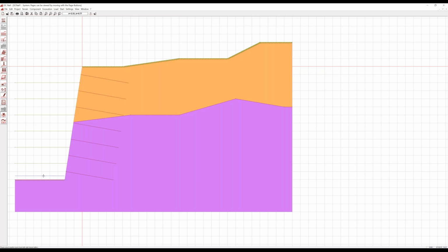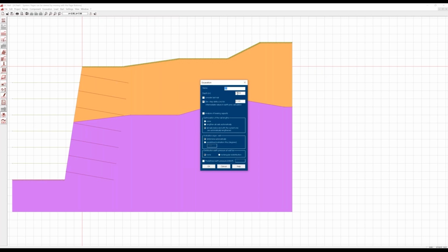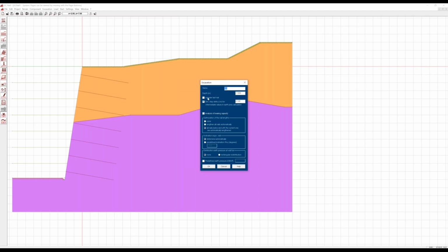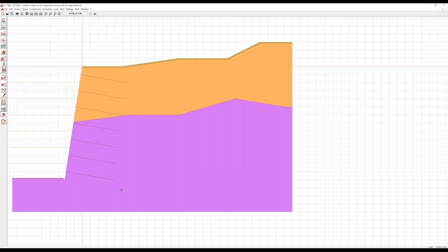I place it here a little higher. And if I edit excavation stage 7, this should be a little higher, 6.9 meters, for example. And the last excavation stage, E8, should consider the last nail. So in this last stage, the last nail layer is present. So we have now 2 different stages.